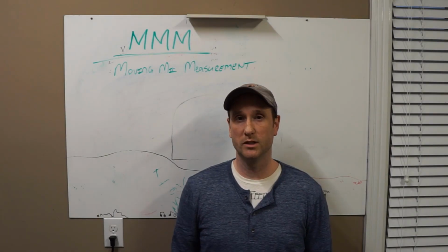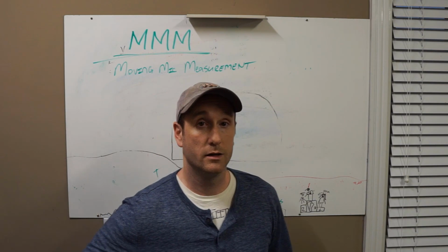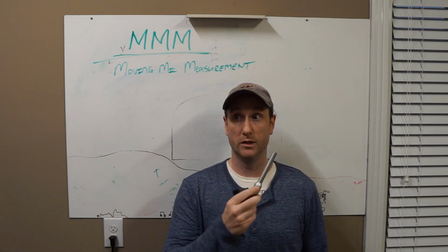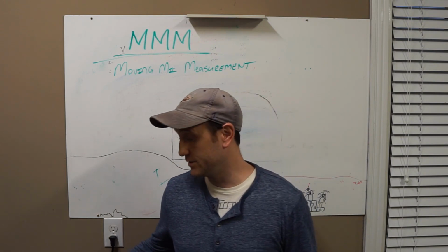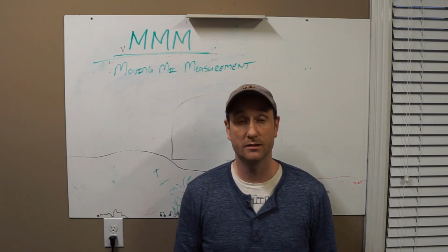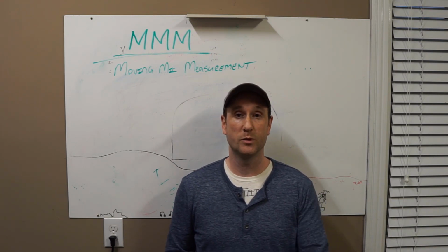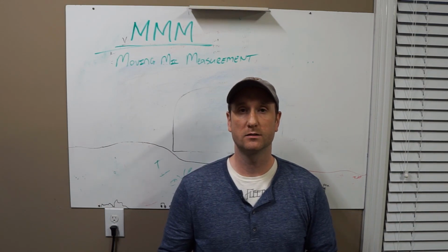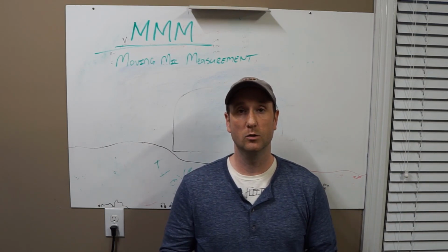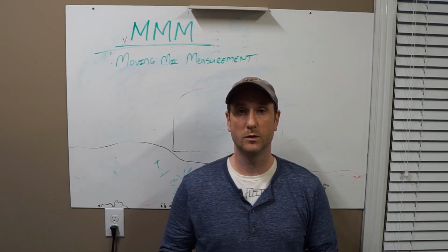A moving mic measurement is a lot what it sounds like, taking a microphone and moving it and getting measurements. What this applies to, though, is RTA, which is real-time analysis, and you would do this for the purpose of EQing a response of your speaker system in your home or in your car system. Normally when people measure the response at their seated position, they'll do so with a single mic measurement only, pointed at the speaker system, and they'll record the response playing pink noise or something along those lines.